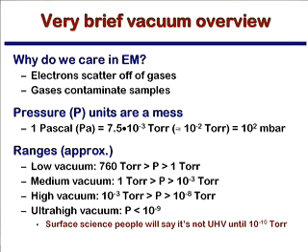And the thing is, to do low vacuum, to do high vacuum, to do ultra high vacuum requires substantially different types of instrumentation, different types of pumps, different types of care with respect to sealing things. And so the compromise that is most usually made in the TEM world is to focus on creating high vacuum around the sample and give up on the extra effort of going to ultra high vacuum, okay? The gains aren't really worth it in the end. There's a couple of UHV machines out there. They're mostly used to do surface science in odd and interesting ways.